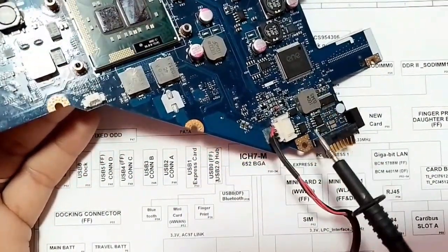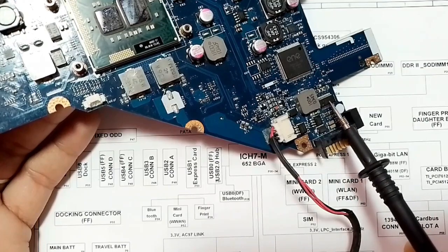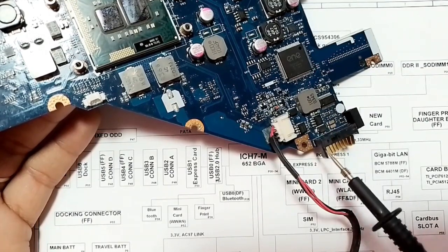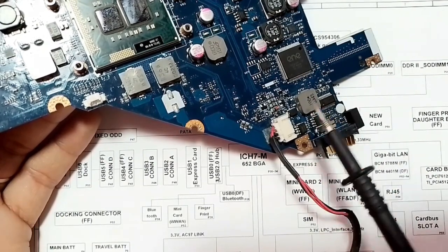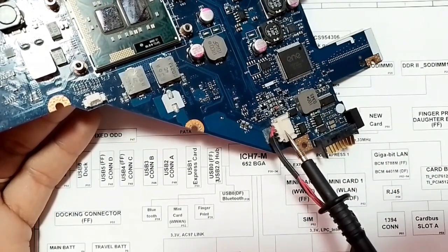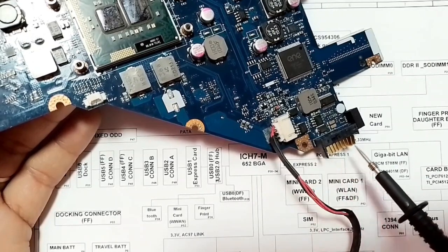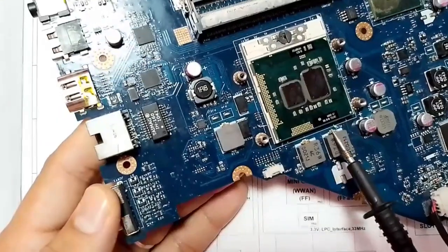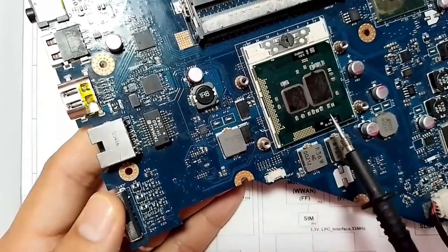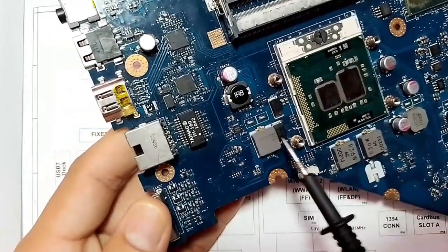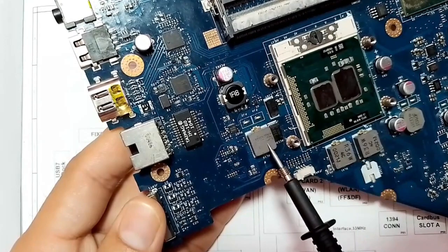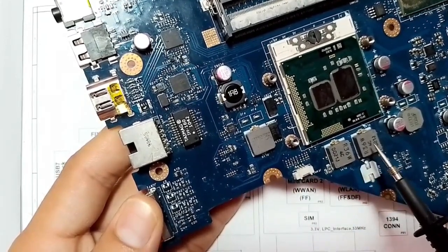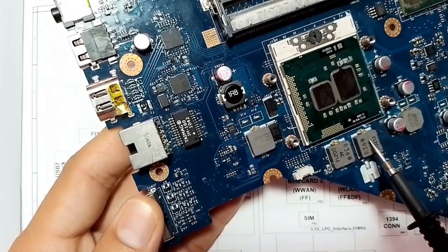Here we have the charge IC, or the adapter battery charger. This is the charge IC circuit where we have the power jack connector, the battery connector, and the power switches or MOSFETs. Here, for this MOSFET, we have 3 channels. 3 channels for this MOSFET. Always, an inductor means a channel.